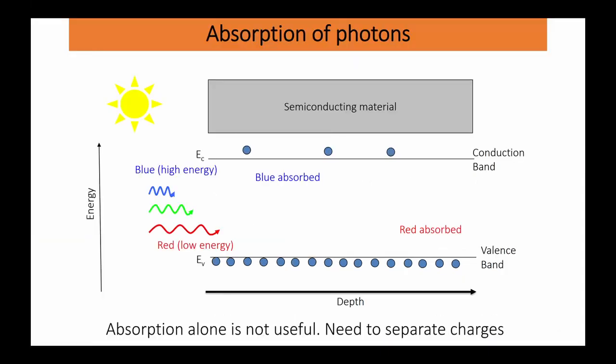Okay, so when we shine the light on a semiconductor, electron hole pairs are generated. Always there is a transition of an electron from the valence band to the conduction band. So the generation of electrons and holes will always be in a pair, so we always call it an electron hole pair, EH. The electrons are in the conduction band, which move, and the holes are in the valence band.